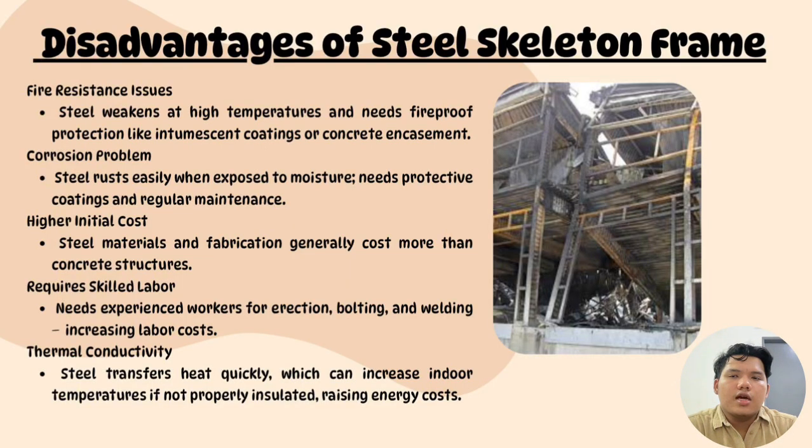The next one is higher initial cost. Steel material and fabrication generally cost more than concrete structure. Next, the disadvantage is that it requires skilled labor. It needs experienced workers for erection, bolting, and welding, which increases the labor cost. And lastly is thermal conductivity. Steel transfers heat quickly, which can increase indoor temperature if not properly insulated, raising energy costs.